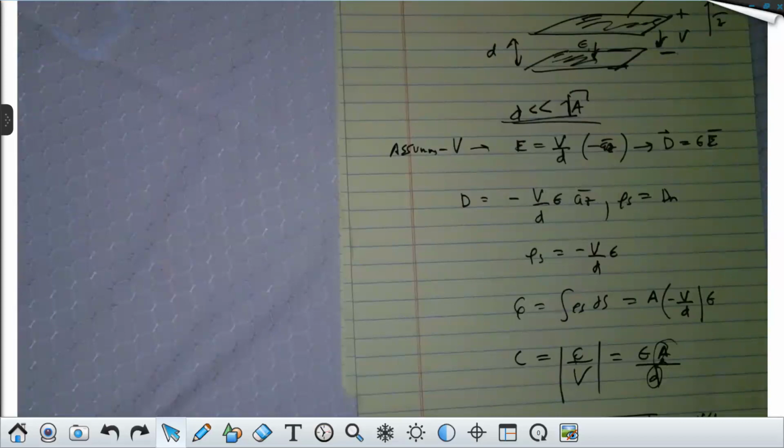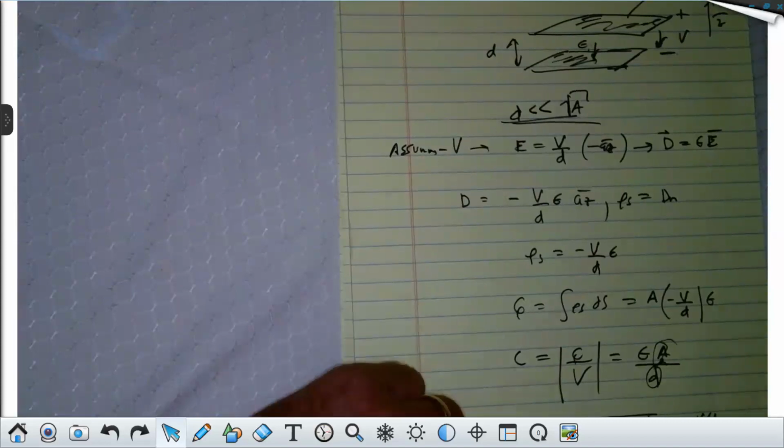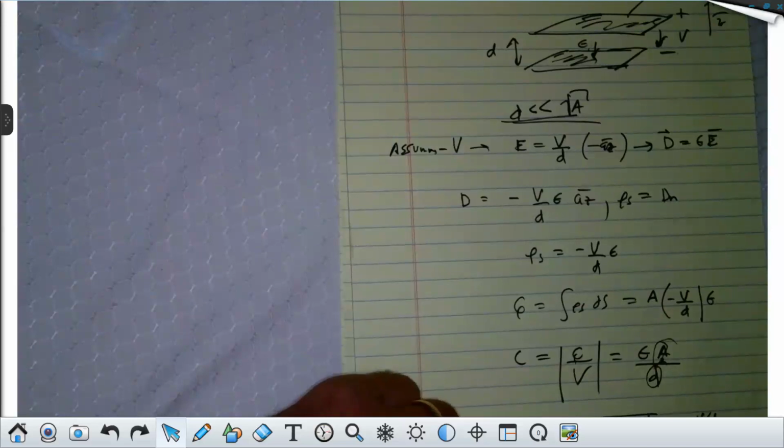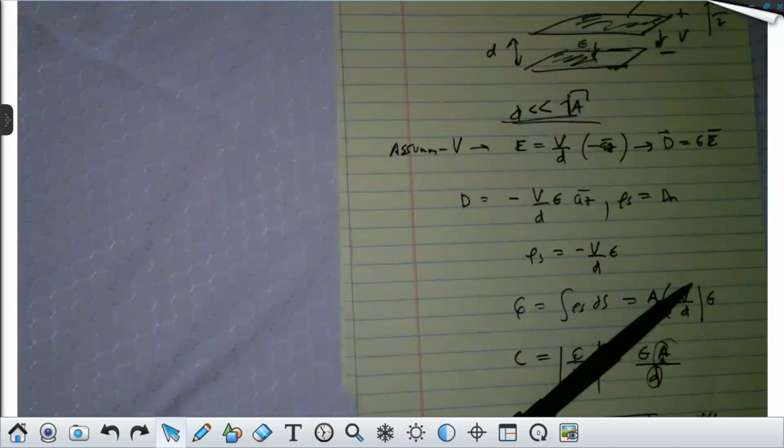And the real problem is that the breakdown strength of the medium you have here is the thing that will limit the value of capacitance. Your value of epsilon is going to be linearly scaling, but if you had something that could withstand like 5 billion volts per meter before breaking down, then you could store a whopping amount of energy in there, regardless of the value of epsilon. But the truth is that it's usually the breakdown voltage of the material that limits the actual capacitance. Now, for air, like around here, it's about 3 million volts per meter. For mica, it's 200 million volts per meter. And if you think about that, that's a factor of 40 better than air as far as the maximum breakdown voltage.